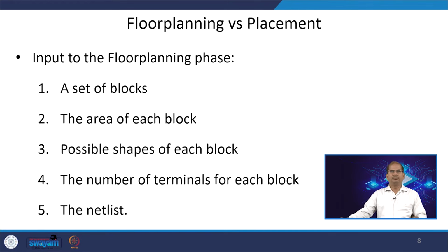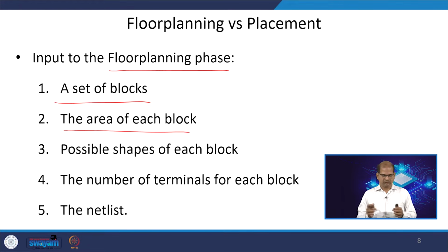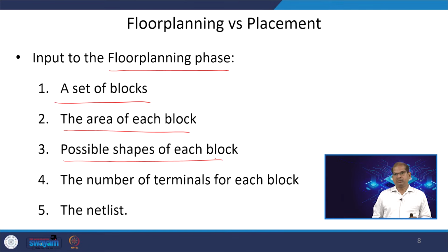We will see what the input to the floor planning problem is and what the input to the placement problem is. First, we will discuss the floor planning problem. In floor planning, what are the inputs we give to that algorithm? We have a set of blocks, and the area of each block. We also know all possible shapes of the blocks. Let us say I have block A, it can have different orientations. So, all possible shapes, basically the orientations